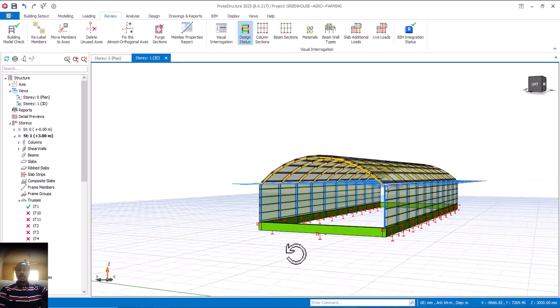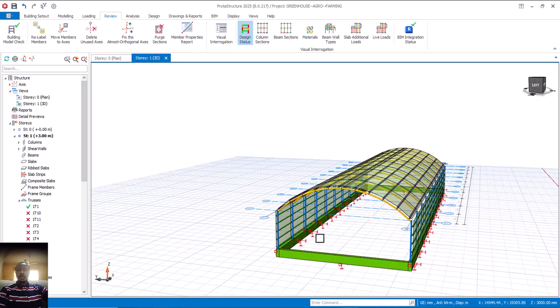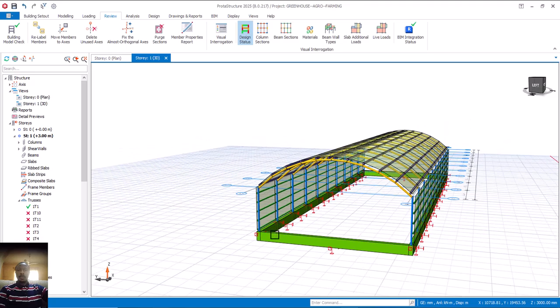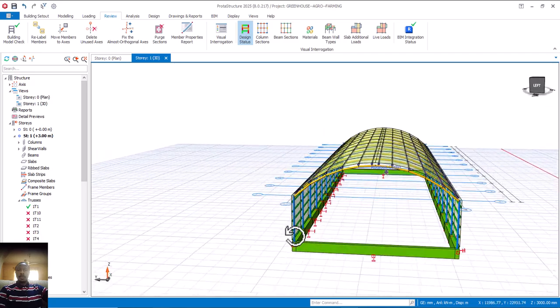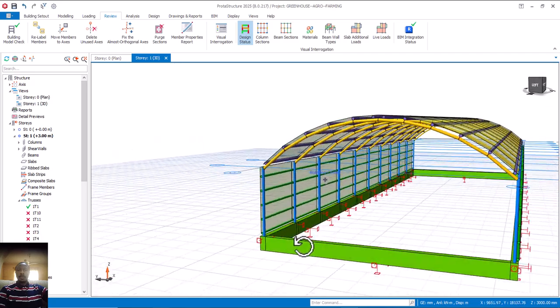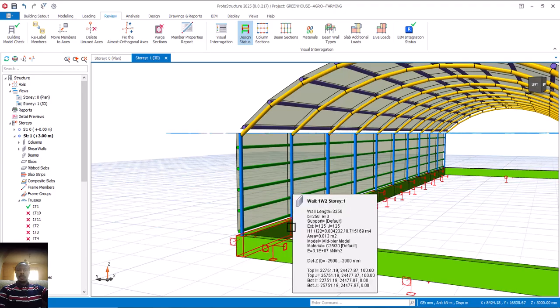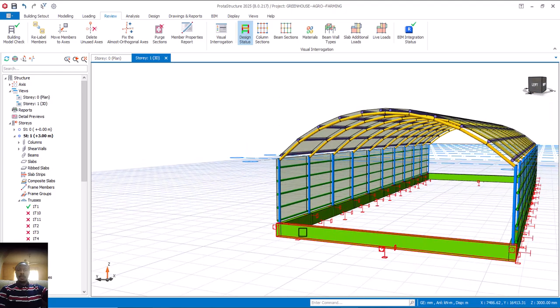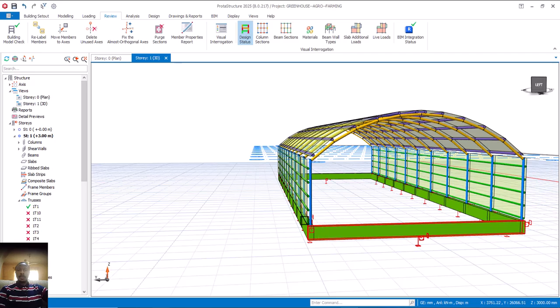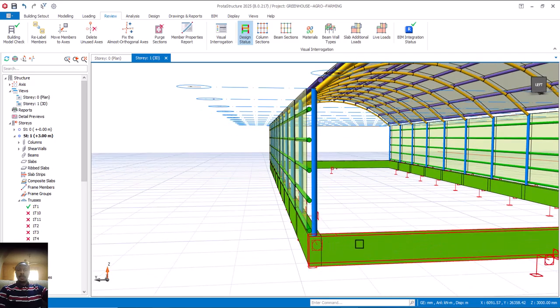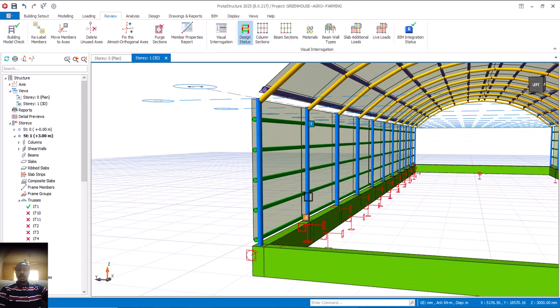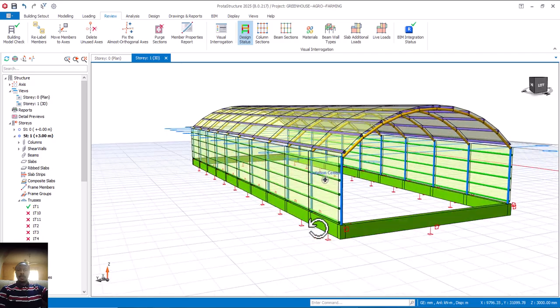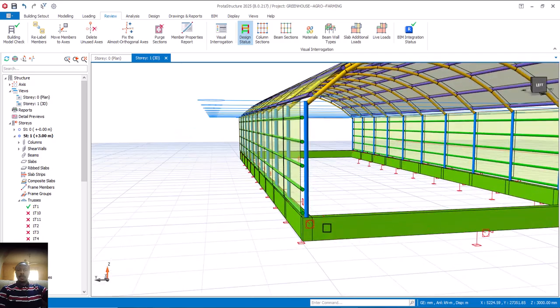Last time I used beam to do this foundation, and you know that for a beam to be able to pass, it requires a column. This particular one we are using is not the type of column for a beam, isn't it? We are expecting this particular one to carry this stanchion, because we call these stanchions. For it to be able to pass design, definitely what we must use is a wall.